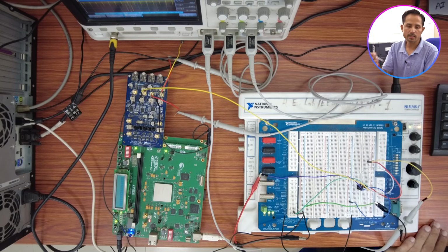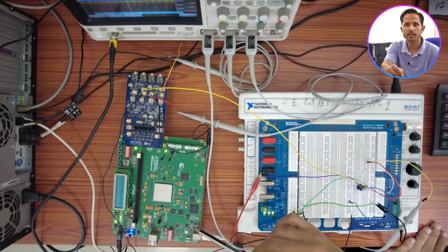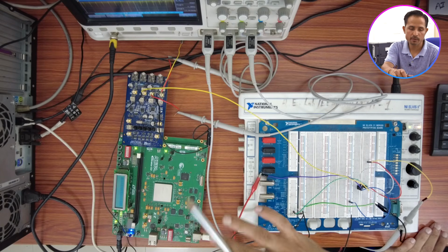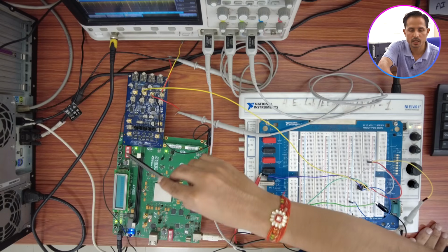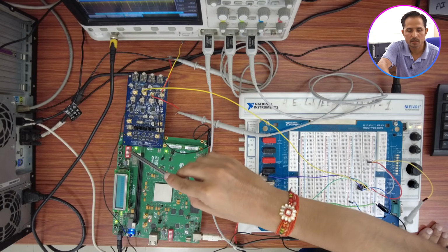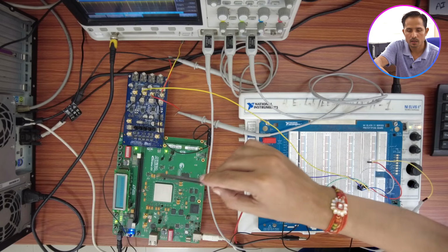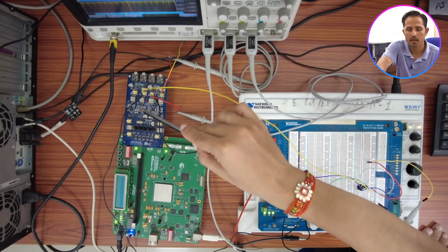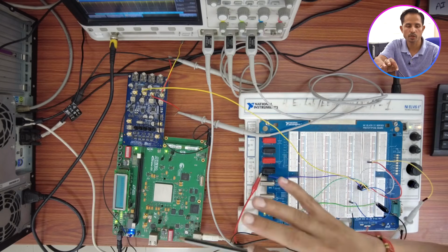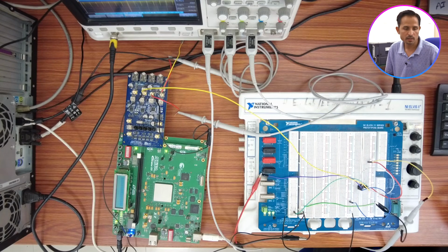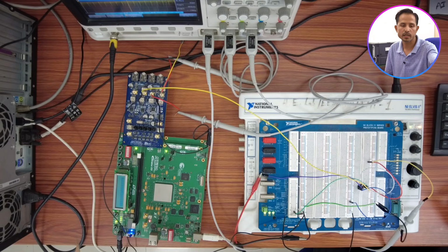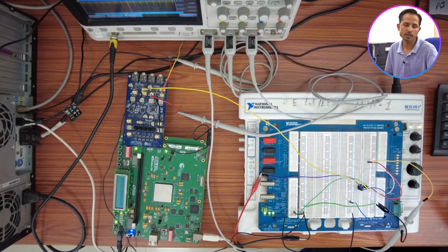Another component is this FPGA board, which is an Altera Stratix III FPGA board. It has many peripherals. This is the DIP switch. These are the user configurable DIP switches. These are the push buttons. This is one of the HSMC cards associated with this Altera board. This is the power supply, and from here this cable goes to the CPU, through which it can be programmed, and it works as the communication between the CPU and this board.